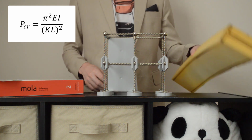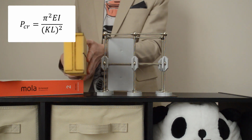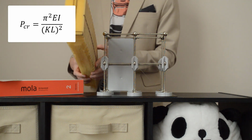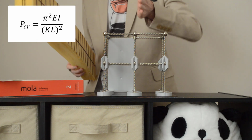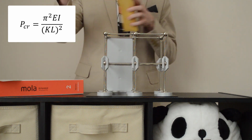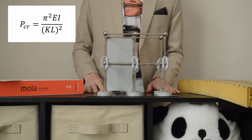But what if we were to provide a rectangular column here instead of this round circular column? And what if we were to orient it such that its strong axis is into and out of your screen? In other words, the strong axis bending is oriented in this longer unsupported length direction.